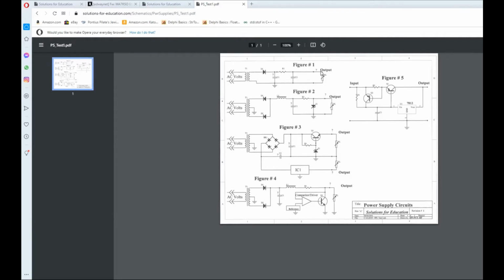All right. This particular one here, if you have a bleeder resistor there, the whole purpose of the bleeder resistor is that whatever voltage is charged up on these caps has a load to go into, even if this load is removed. It might take several seconds or maybe a couple of minutes to fully bleed this thing off.